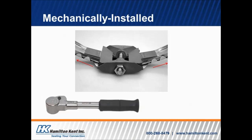It's very easy to install, so that's a positive. The thing that we find is probably the most problematic is that they can be over tightened. So we definitely recommend using a torque limiting ratchet. And the good thing about it, I guess, is that it can be adjusted in the field, but that is also maybe a downside, that it can be adjusted in the field.